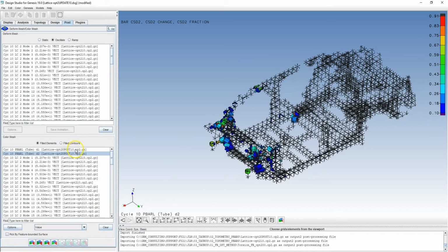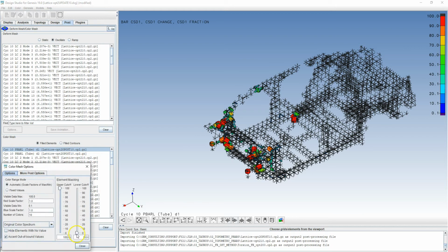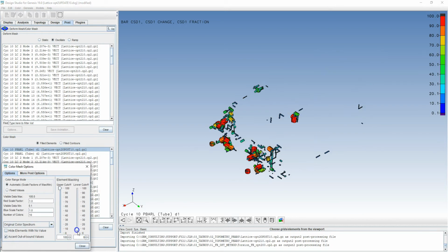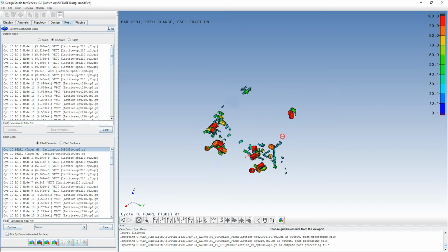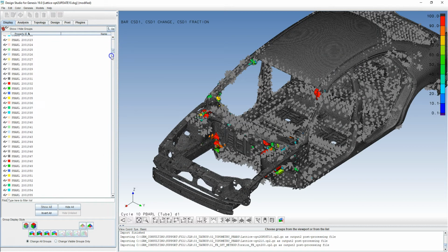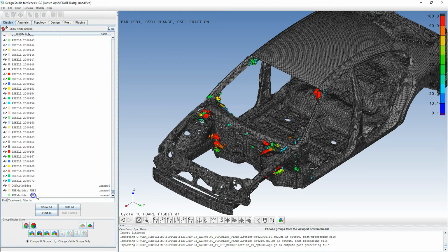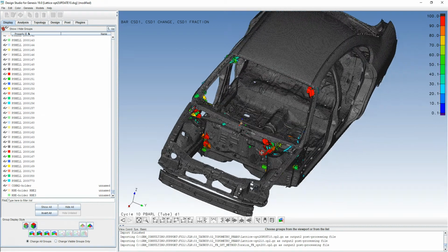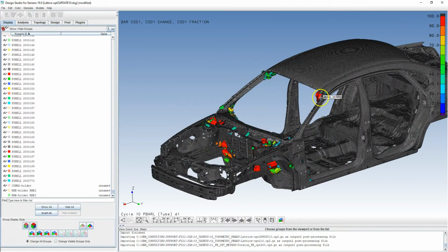Here, if we want to hide any results, so any diameters under a certain amount, we can just simply choose a value to slide them by. We can key that in if we want to. Anything less than maybe 20 millimeters is off screen. So we can look at those, and then we can overlay those with our overall model by putting everything back on screen, like so. Hide those RV3s. So you can really start to see where the improvements are being made.